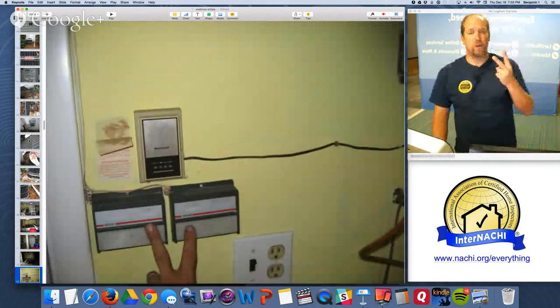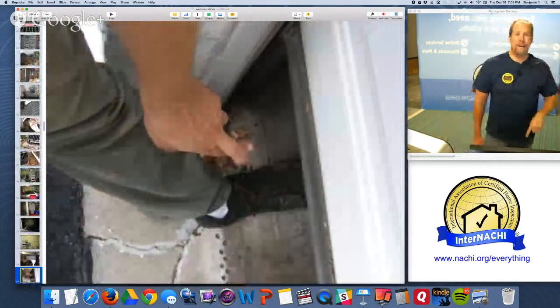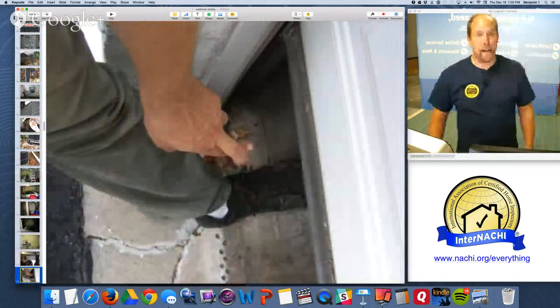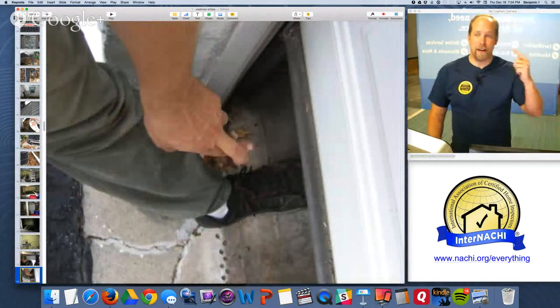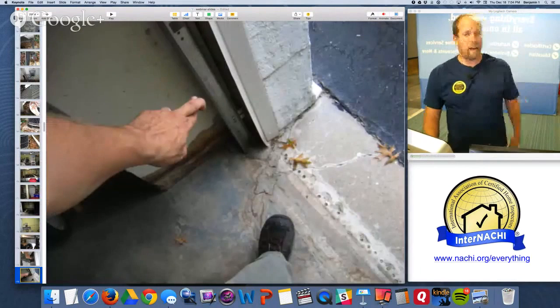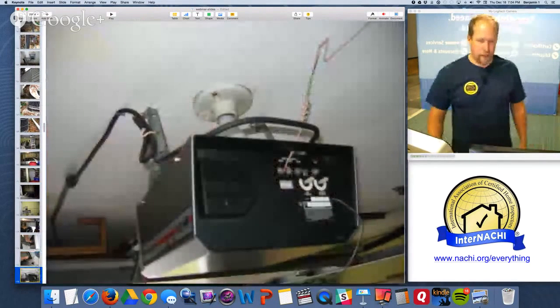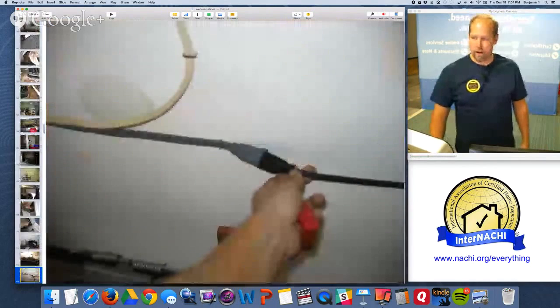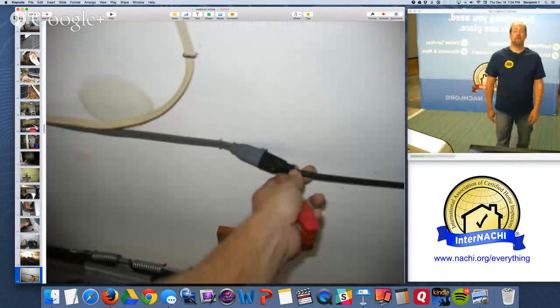I've got two garage door openers. First thing I like to do is open them up and close them and test the safety eyes, the reverse laser beams. And they're not there. They're not installed. So again, an X tells me not installed. There's one of the units installed there, and it's plugged into an extension cord. Extension cords are for temporary use only.